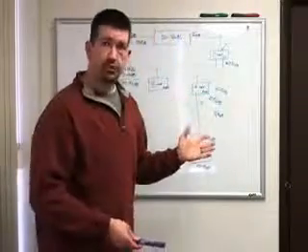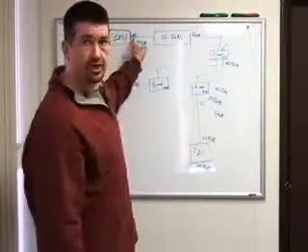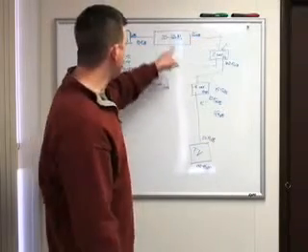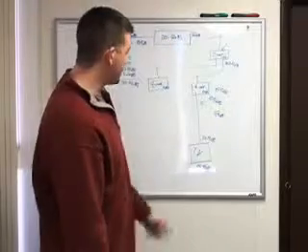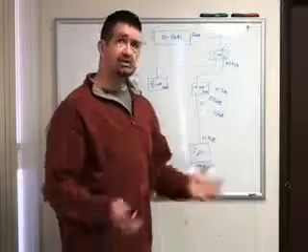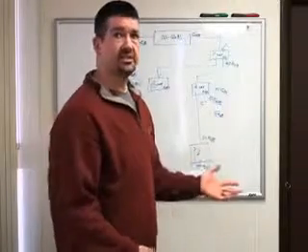In a case like this, you would want a signal meter here to know what your cable company is supplying you with. You want a signal meter here so you can adjust the output of your amplifier. And of course, when you're all done, you want to be able to verify the signal that you have at the end. And that's just using it for the installation of the system.